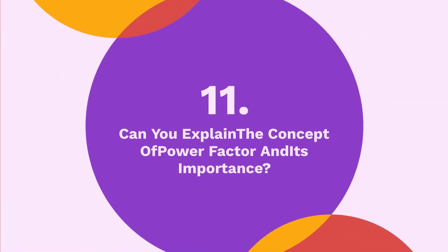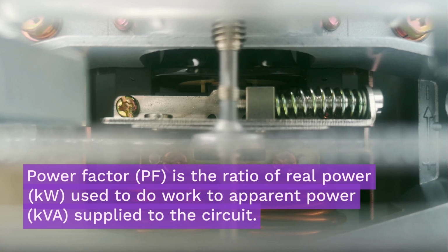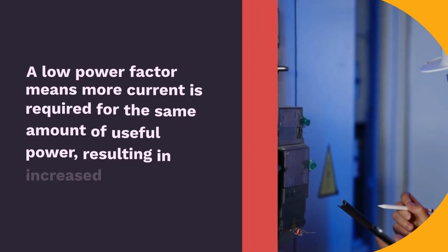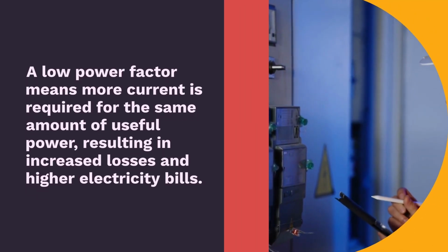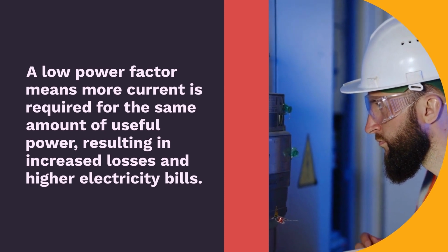11. Can you explain the concept of power factor and its importance? Power factor, PF, is the ratio of real power, kW, used to do work to apparent power, kVA, supplied to the circuit. A low power factor means more current is required for the same amount of useful power, resulting in increased losses and higher electricity bills.